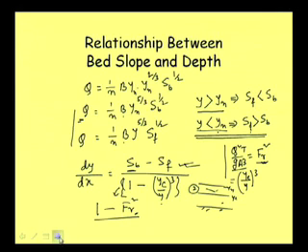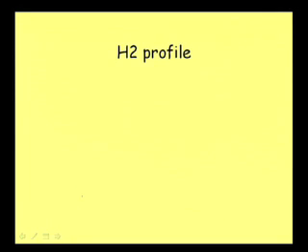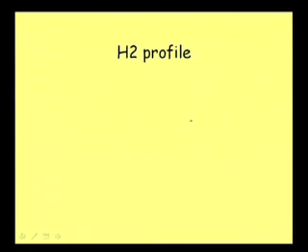And well, then for H2 profile, definitely we will have to use this sort of understanding, because it is advantageous here. Well, let us draw one horizontal bed. You may have a question: when it is horizontal slope, how will flow occur? Because for open channel flow the driving force is the component of gravity force acting in the direction of flow.